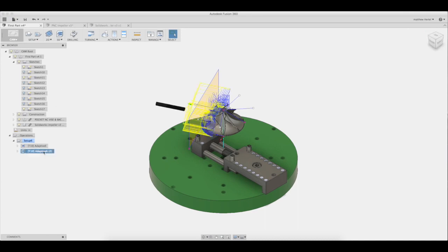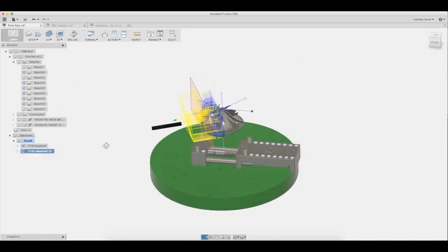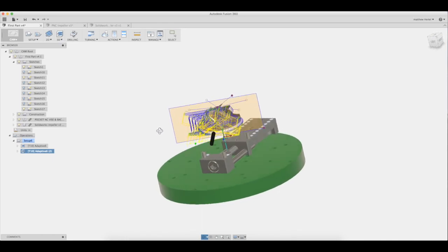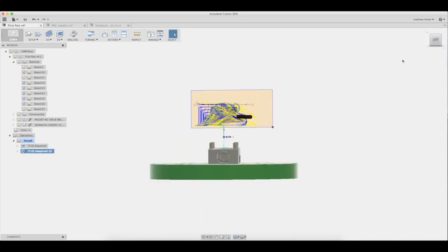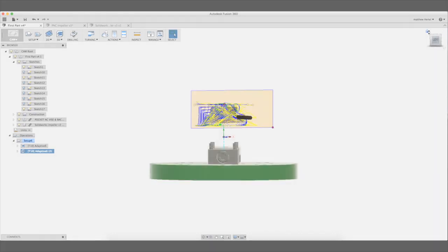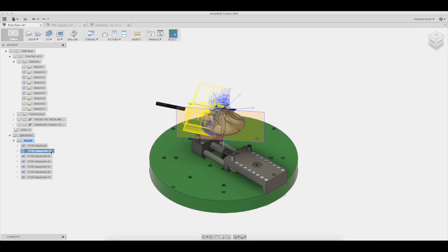As you can see in Adaptive 6 number 2, the toolpath does not machine extra material where the material has already been removed from a previous operation. At this time, create the next 5 toolpaths for the remaining 5 segments. Now that all 7 toolpaths are created, we can do a quick look and make sure that all the toolpaths look correct. Be sure to check several angles and be sure that the depth does not exceed that of the cutter flute length.